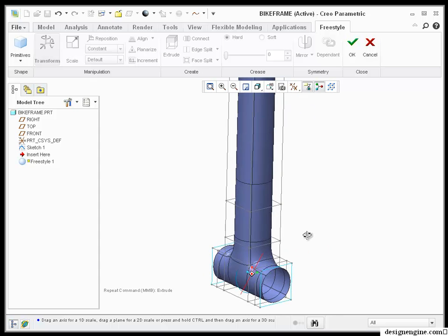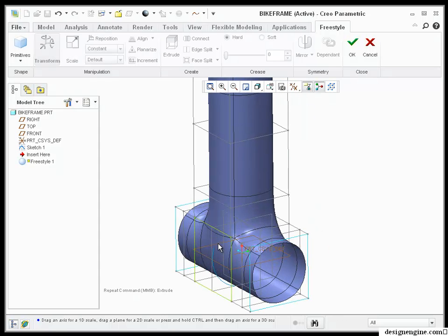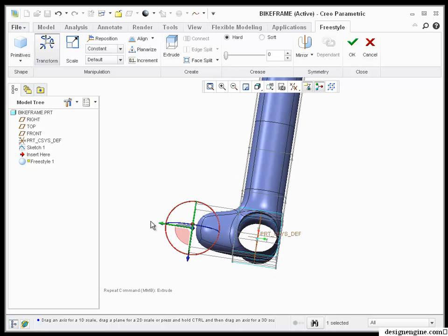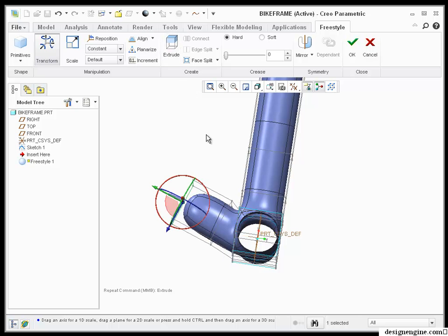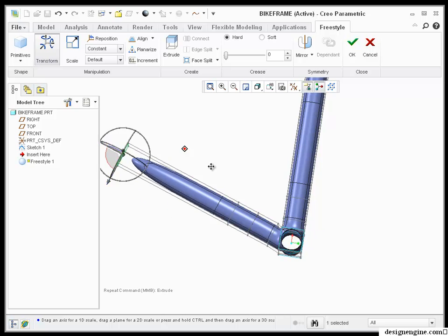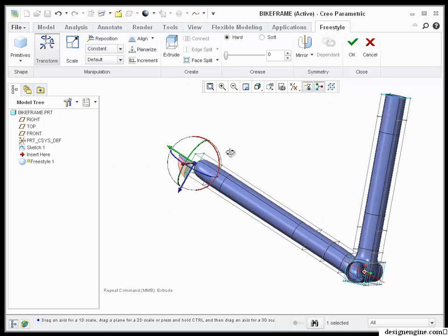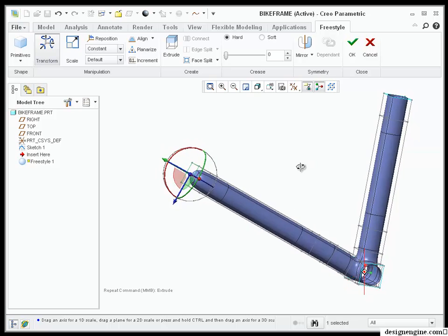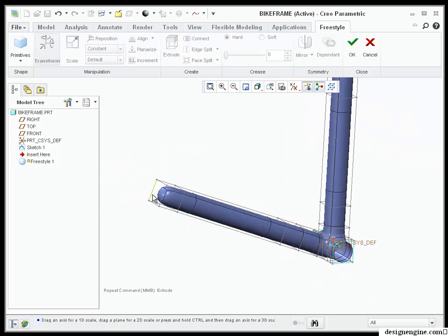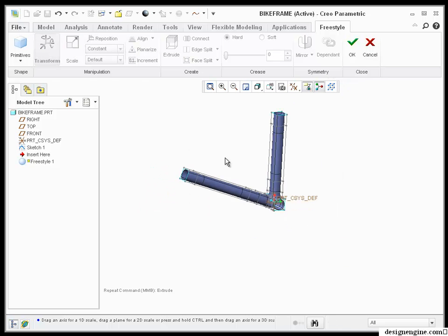Now I'm going to do the same thing for the up tube here, except I'm going to go ahead and extrude it out, and you can kind of see how I can kind of leverage that. I'm going to rotate out here, and now I'm going to extrude the face again, middle click a couple times. This one I'm going to go relatively far with, and then one more at the top. That sort of helps me organize my geometry, and I could click delete there if I wanted to.